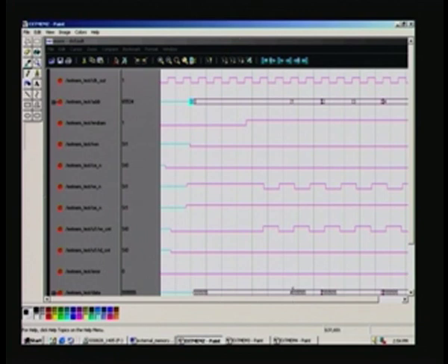That is the reason why it is changing here at every write point, and the address counter is also changing here, 0 here and then 1 here and so on, and it keeps going. And the actual RAM is enabled only at this point of time. Therefore, it starts functioning only from this point of time. In fact, from the subsequent positive edge only it is actively processing.